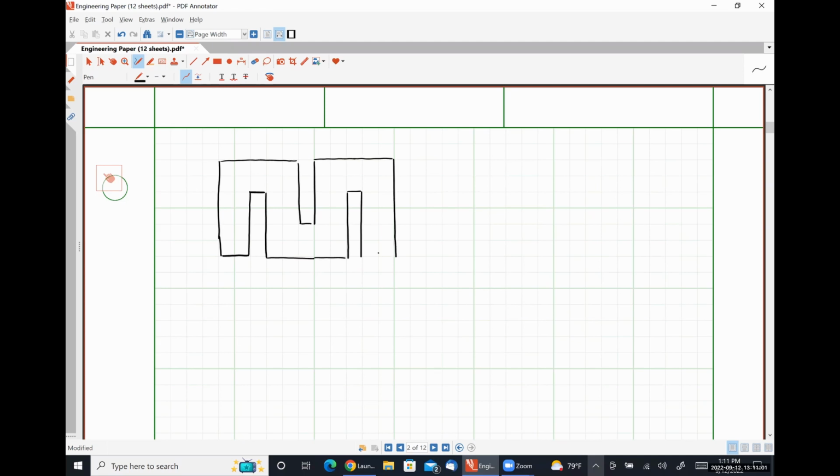So in a serpentine resistor, like so, I'm going to go ahead and subdivide this up into squares so we can kind of figure out what's going on here. Everything behaves exactly like we would expect it to when adding up squares, except in the corners.